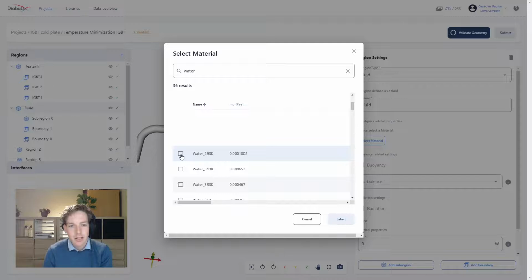In this case, it's not necessary to evaluate it temperature dependent, so I will choose to fix the parameters on, let's say, 20 degrees. Why is it beneficial to fix the parameters to a certain temperature? The computational resources that you will need to run this case will be lower, since doing that in a temperature dependent way is from a computational perspective much more intense. So let's keep it easy now and just select the water at the temperature of 20 degrees.